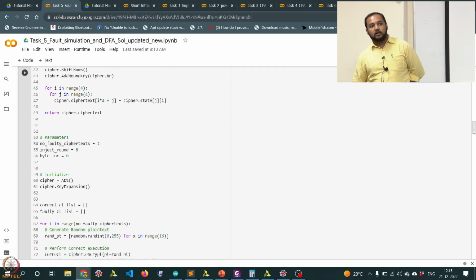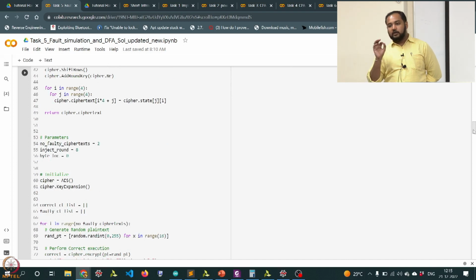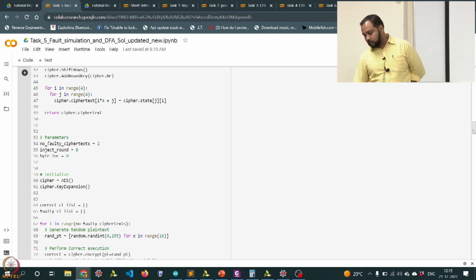Clock glitch faults are just for demo purposes, but for a clock glitch fault you need to create glitches in the clock tree of the FPGAs. There are also voltage faults. There are commercial devices available like ChipWhisperer, where you can create voltage faults and clock glitch faults. Even EM faults are possible in ChipWhisperer. There is a small device known as CW305, which houses an Artix-7 FPGA, where you can create all kinds of faults if you want. ChipWhisperer is commercially available.